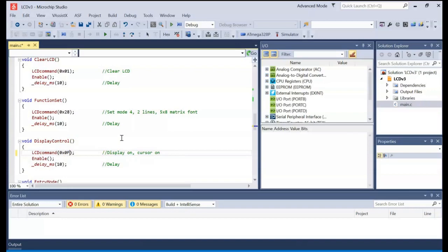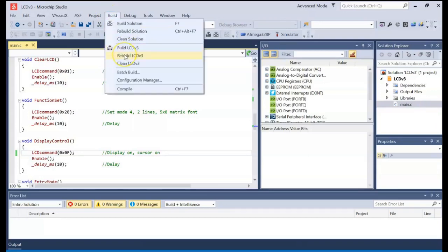If you recall, if you go back to the early explanation, you'll see that the last bit, the least significant bit, has to be set to a 1 for a blinking cursor. So go check the datasheet out and play around with it. That would help you to understand the LCD module a bit more.